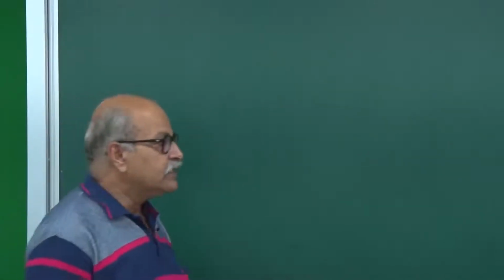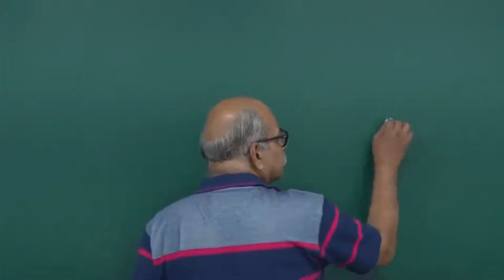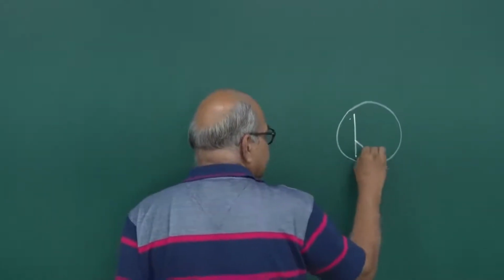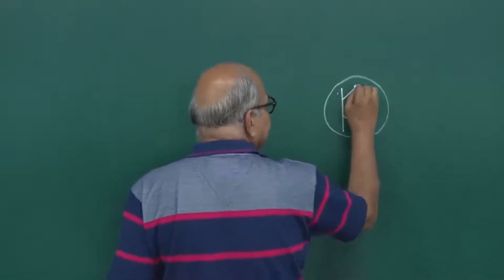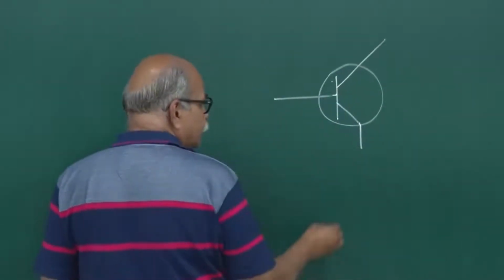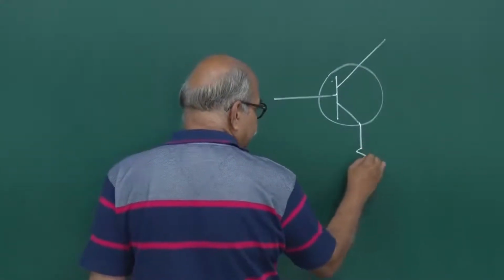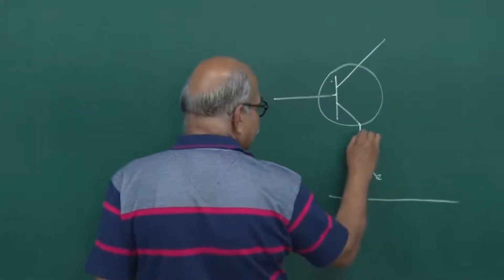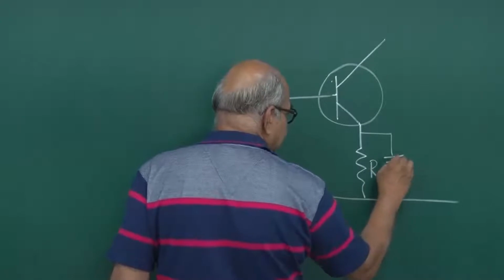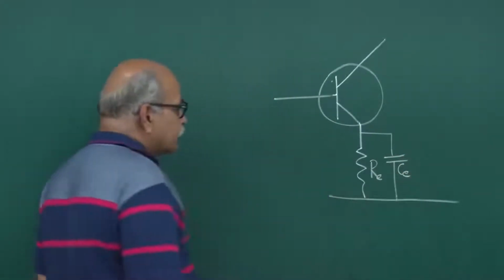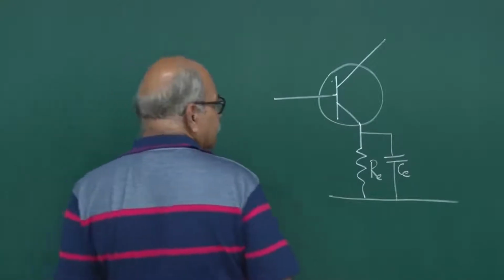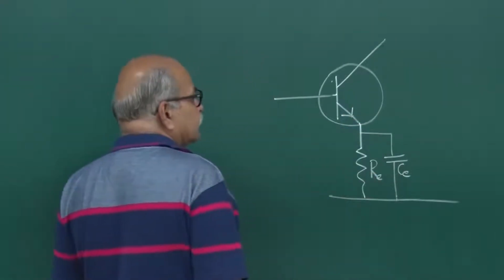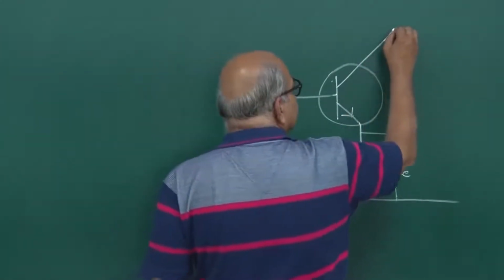So, in a transistor amplifier in common emitter configuration, you have this emitter here and collector here, base here. Then you put this to ground, some resistance. In actual case you also put some capacitor, so that this alternating signal is bypassed from here. And then this side should be forward biased, and this is an NPN transistor, so this should be forward biased. So, we put up a